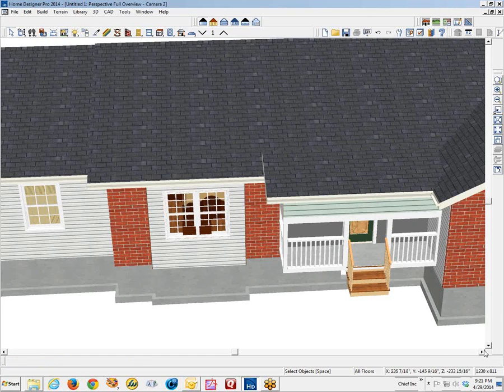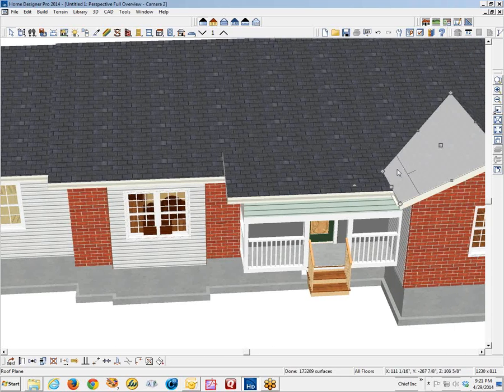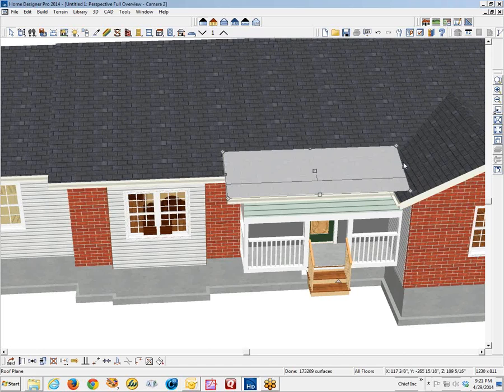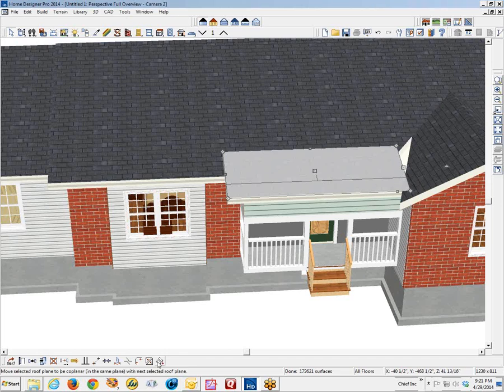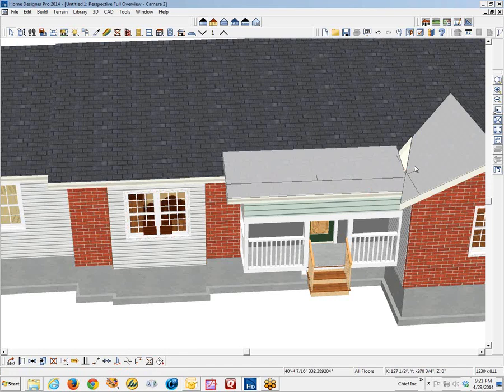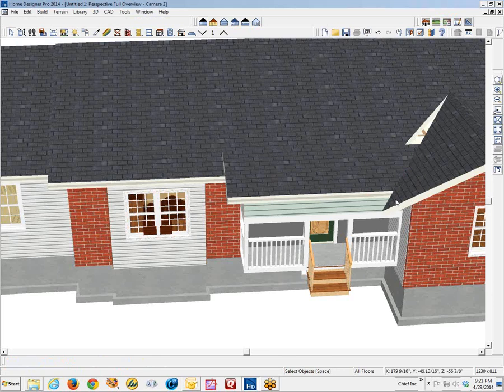Now, there needs to be an extra line in this roof plane to match this edge right here. So I think I'm just going to manually take that up roof and then click here and use the join roofs tool and just see what sort of result I get. Yeah, it's about what I expected. Now here, I'm going to manually fix that up.